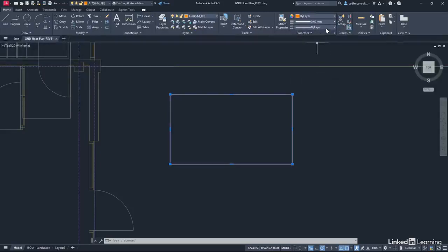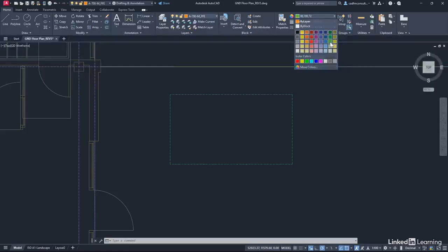And I'm also going to change the line type, like so. Let's use grid line 1-2, which is the grid line type. You can see the purple grid lines to the left. So that's updated. Let's also change the color. Let's go for that green there. So it's now a green color as well. So if I now hit escape a couple of times, can you see it looks very different?